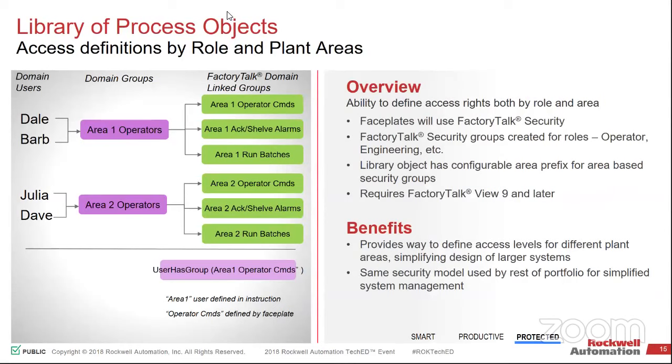Can we change that security while we are running the system? Yes. So there, you can change the security based off of the FactoryTalk Directory side of it. You can make modifications from there. You can make modifications as part of the domain. So if it's tying in from a domain and getting your authentication access, you can always make changes there. And then there's a macro setting that you can change your settings via the macro. So the macro may not let you do it online, but the other two do. So.